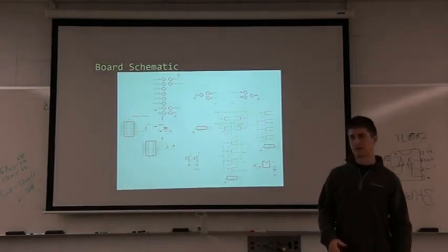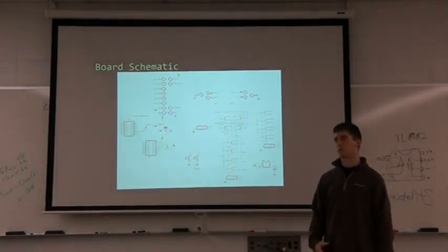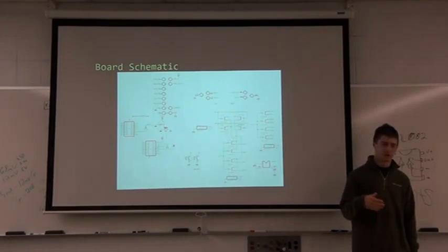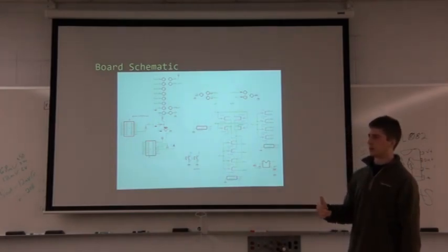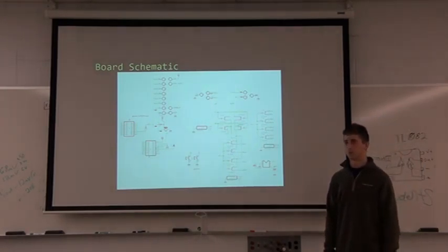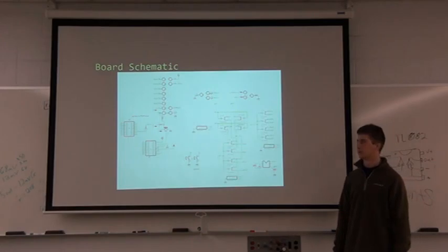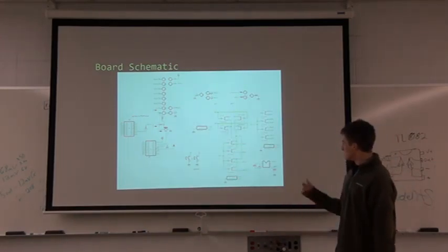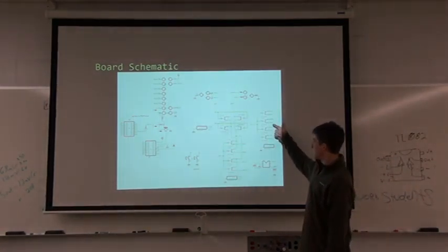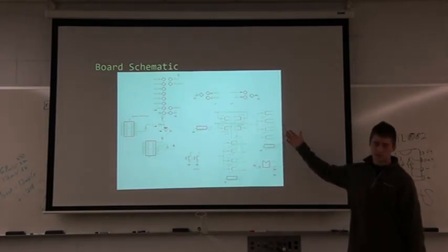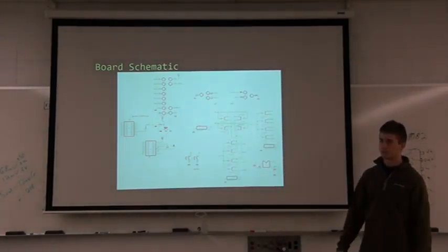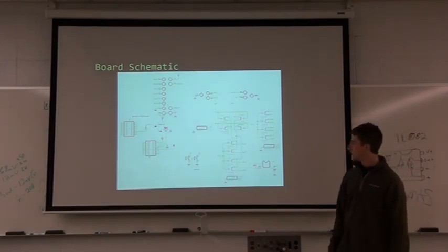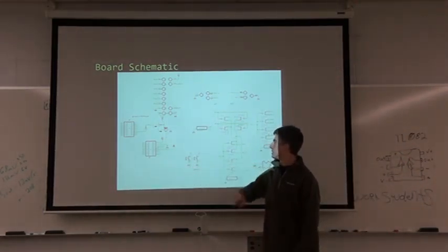It is a voltage converter that will take an input supply and create a negative biasing supply that can supply up to 0.2 milliamps. For these CMOS switches, that's fine to have 3 of them. They use microamps, so I can definitely use that as a biasing supply. These are those switches that I was talking about.